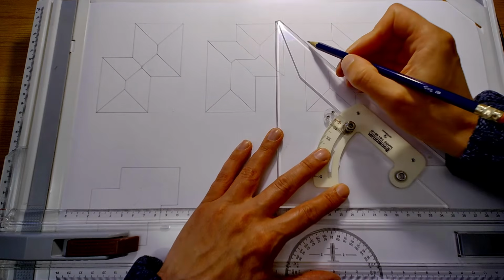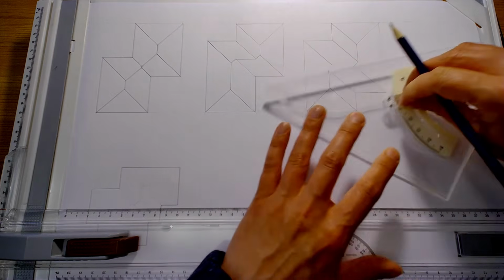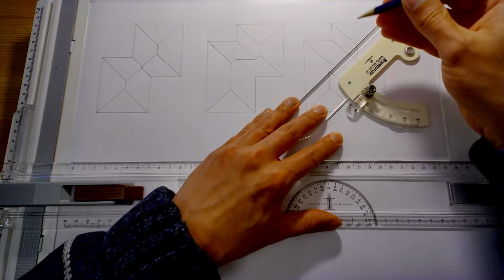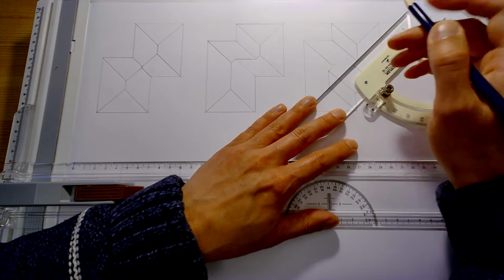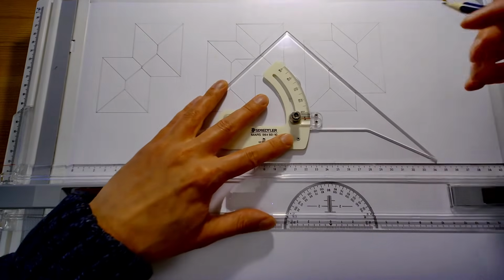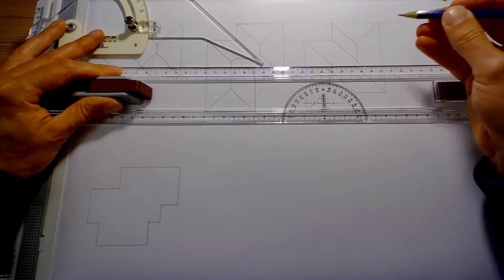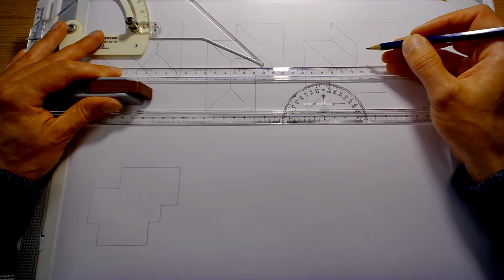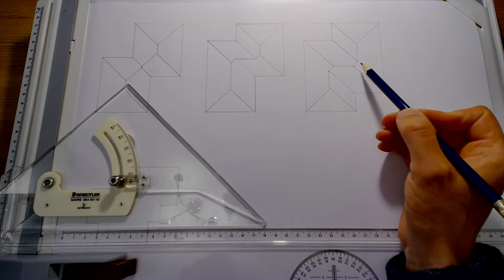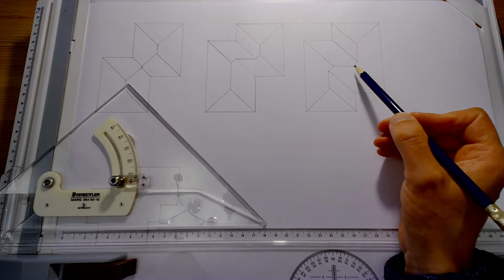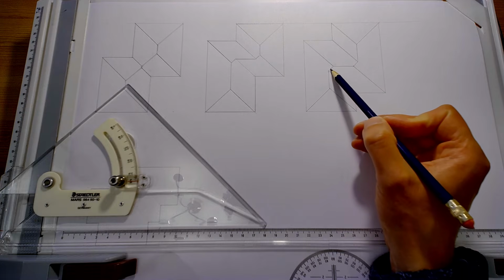And then we can run that hip up here, and this has a hip coming off this point here to where they meet. And then where they meet is where we can now run a ridge between those points. So notice the difference there, how now we've got this extra raised section on this side.